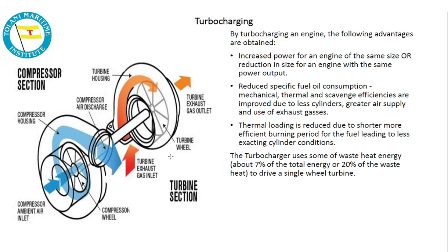Now we come to the turbocharging. By turbocharging an engine, the following advantages are obtained. Increased power of an engine of the same size, or reduction in size for an engine with the same power output. Now you see a turbocharger basically consists of two elements. One is the compressor, the other one is the turbine.